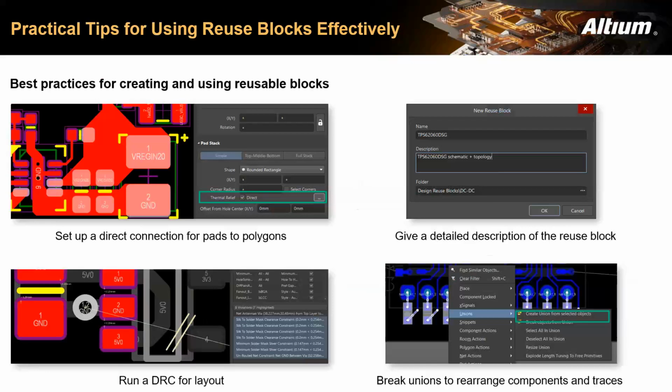The fifth tip is polygons and pads. I recommend that you configure the connections for the pads to polygons in the reuse blocks. Otherwise, when you place your block in your project, the connections are handled by the destination design tools, which may not be exactly what you expect.